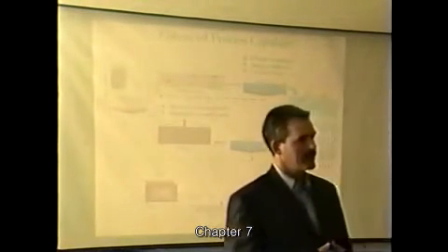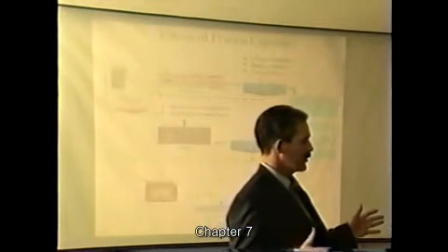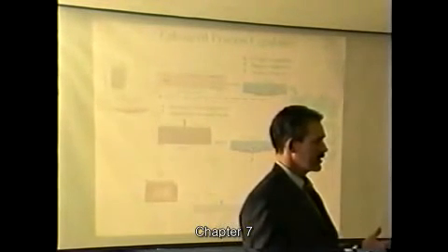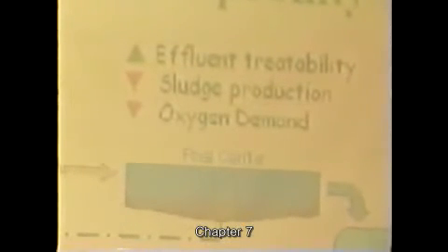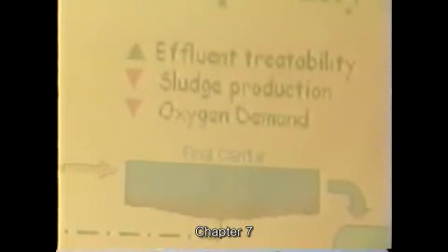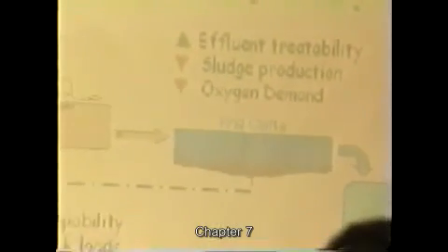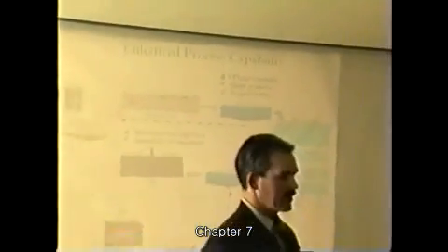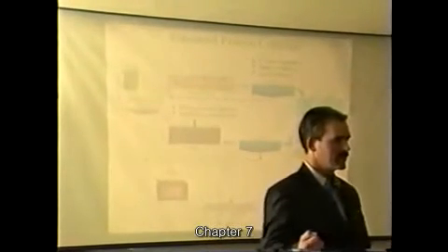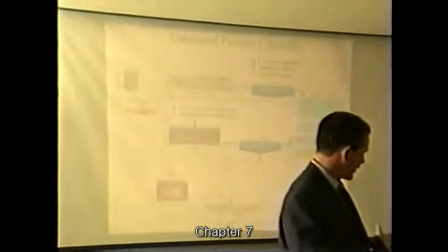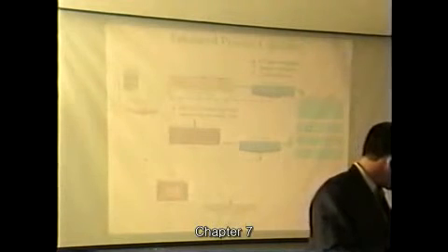Your oxygen demand decreases. In other words, if your plant is overloaded, you would require additional aeration to be able to cope with the organic demand, the oxygen demand. We say, if you introduce Archaea, you don't need the capital investment of buying more aerators, putting in electricity, and the maintenance costs involved. Archaea will remove those metabolic byproducts to methane. And the additional benefit then obviously is the reduced sludge production.